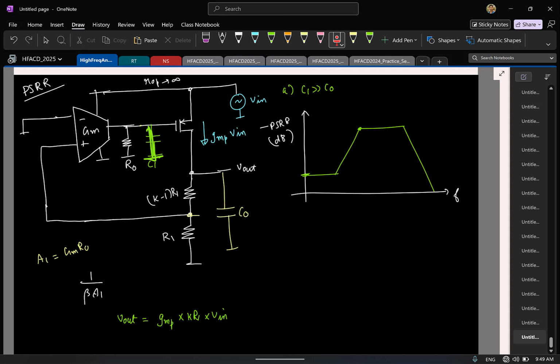But now the way I have wired up the circuit is such that when the capacitor is acting like a short circuit, the gate is also shorted, it is not responding. Right? And remember, C1 is a cap that we are putting. So we have right now put a capacitor from this node to ground. Is there some suggestion you can give me by which, even if the capacitor acts like a short circuit, if I make any change at the source here, I should be able to get that change here? Because anytime I have a change, if the change is reflected to the gate, I am fine. That argument is clear?